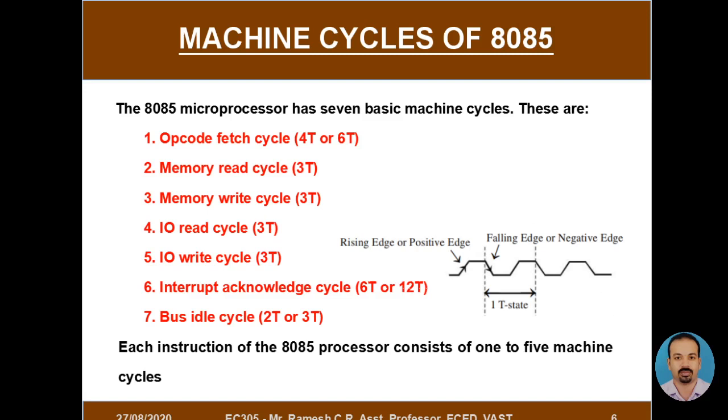So if we go for the timing diagram of the opcode fetch cycle, it consists of the clock signal, the status regarding the address and data bus, how the values have been shuffled, and what is the value for the IO bar, M bar signal, S1, S0, read, write, etc. All those control and status signals will be plotted in that particular waveform representation.